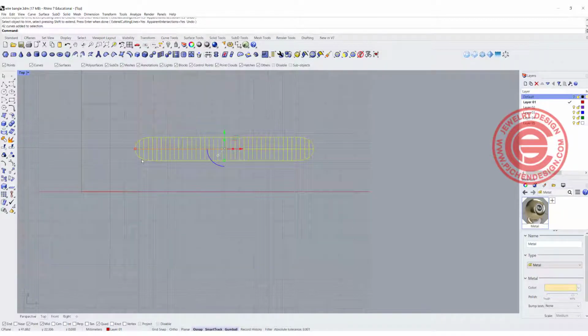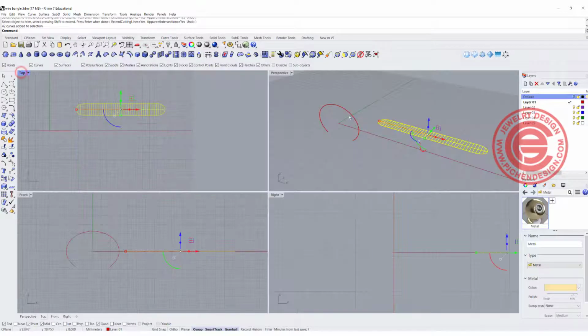Now we are going to twist this one first. There is no way you can twist something that is already on there. Take it back, there is a way, but it is an easier way when you work on your design when it's flat. So what we are going to do is use the twist command.